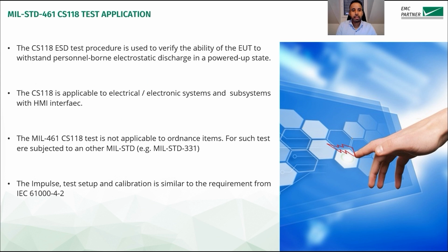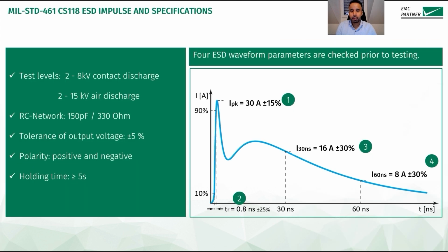The CS118 test is used to verify that electrical and electronic systems with human-machine interface, HMI, can withstand electrostatic discharge, and the test is only performed in powered-up state. Explosive devices are excluded from this standard. For example, munitions are covered under standards such as MIL-STD-461. The CS118 test is, as I said before, based on the requirement of the commercial ESD.